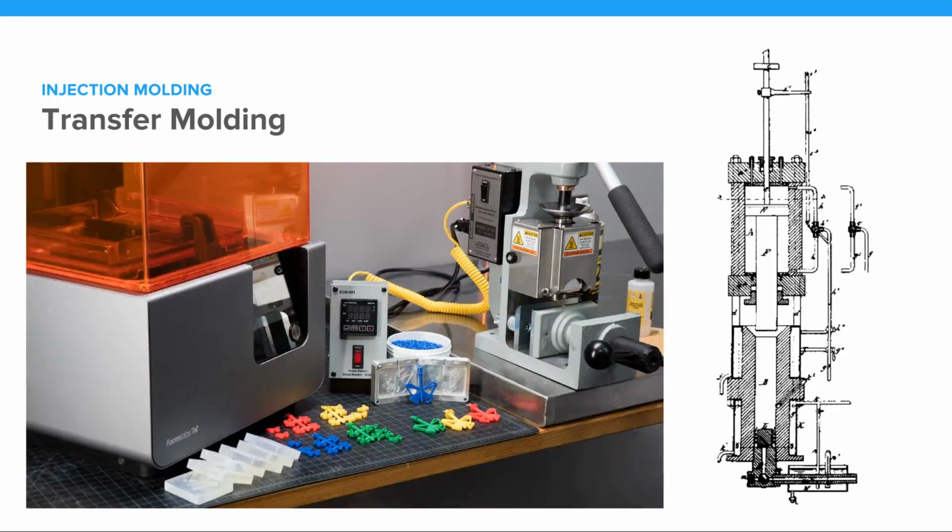You fill up a plate or a little cup called the pot with plastic material. The material is heated, and then it's injected by pulling down a lever, which shoves it into the mold. Again, we did a bunch of testing on this. I'll share some of the results during this presentation, but if you get a chance, I really recommend checking out the white paper online. Just Google Formlabs injection molding white paper and you'll find it.